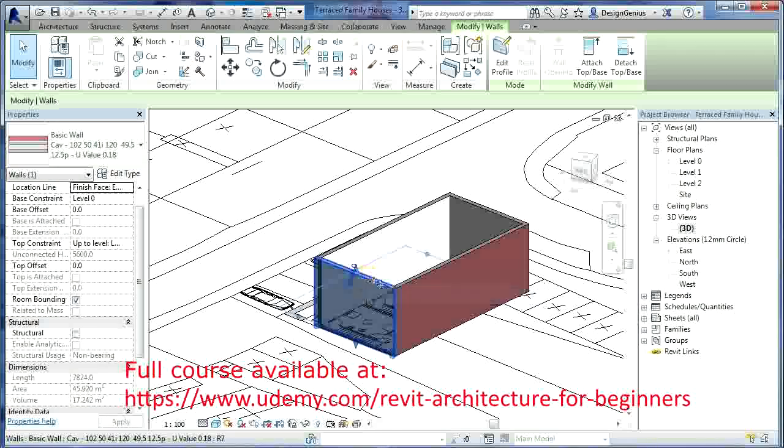I'll bring this particular tutorial to an end. It's past 20 minutes. I didn't want to go too far, just to keep the tutorials very short. So in this tutorial, you learned how to import drawings or layouts from AutoCAD. We learned how to build the walls and build the components. We learned how we can modify the standard components in Revit to meet the thermal performance that we want for our building. We went on then to draw the wall around our building.